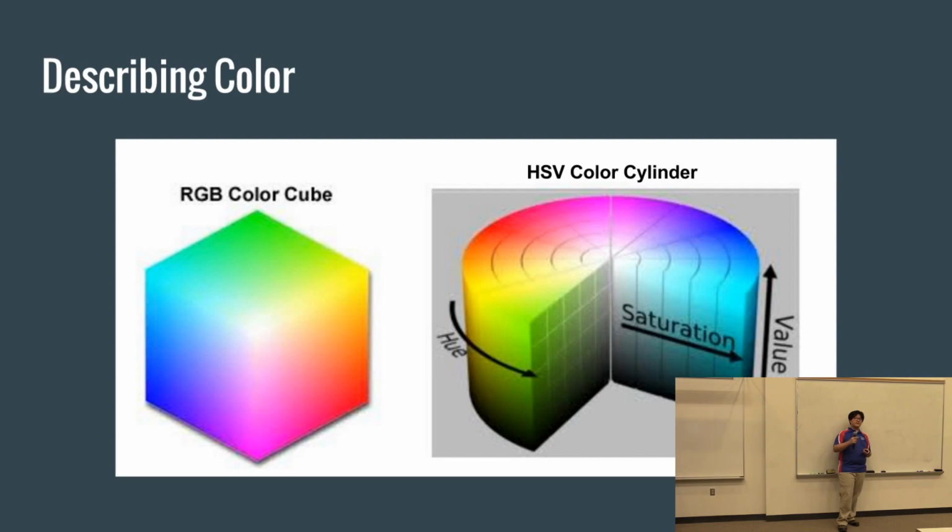If you shine a light towards the retroreflective tape, the light bounces right back towards the light source. So if you have a camera right next to the light source and you shine a green light towards the retroreflective tape, the green light is going to come back to the camera. If you have a green LED next to the camera, you point that camera and turn the LED on to the target, that target in your frame is going to look very green. Then you can use the HSV thresholding I was talking about to pull only the green pixels out, rather than having the other pixels in there.